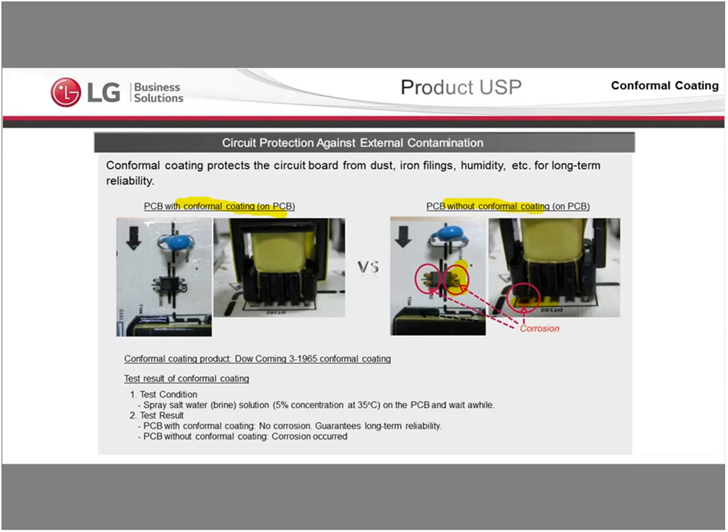It's really important. This is not to be confused with IP5X. IP5X, ingress protection 5X, is an actual certification. This goes a long way. I would say about 85 to 90% of the way towards IP5X. It will stop dust, iron filings, humidity, and other things from long-term problems with the screen, but it is not